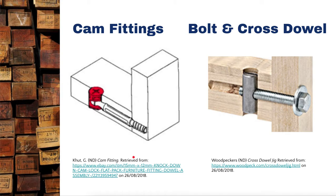Cam fittings. Okay, now for a cam fitting, you basically have a little bolt running through the center. It's got a little screw thread on the end that grips into the end timber. And then when you put these pieces together, the bolt slides through this hole and into there. You turn the Phillips head, and it actually locks around the bolt and stops those two pieces from falling apart.